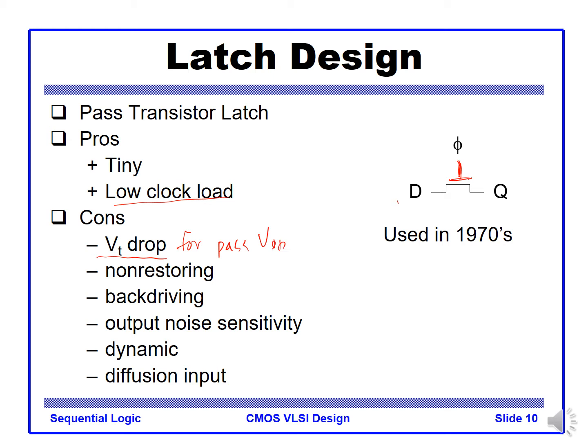When you apply VDD here, we want to charge the load capacitance, but by the current direction, this is gate and source, right? For that switch to be on, VGS needs to be greater than VTH.